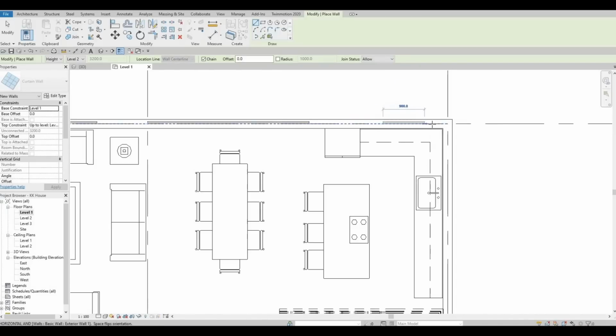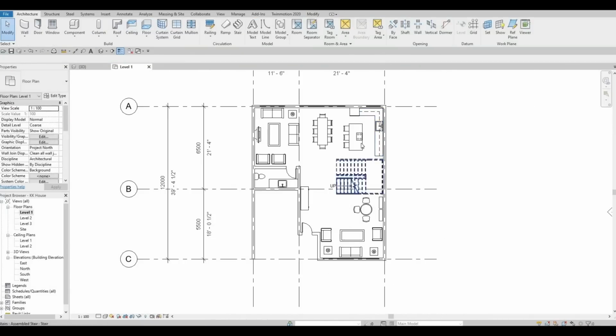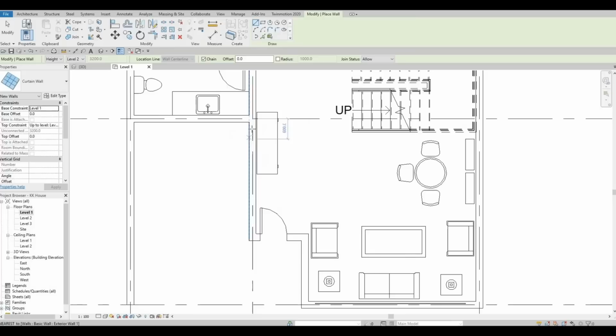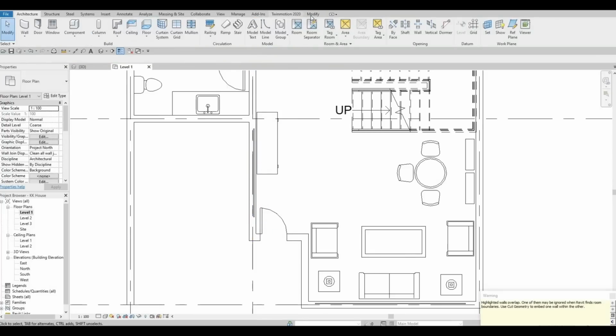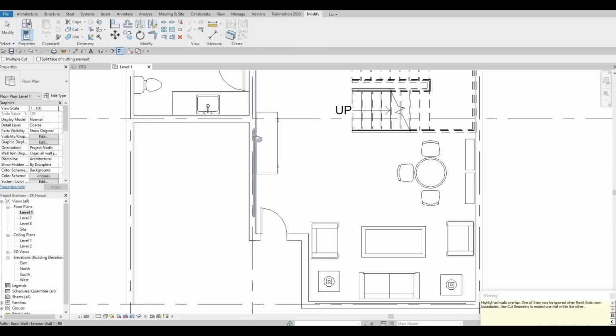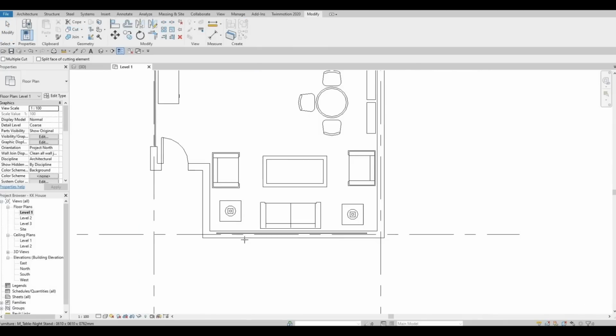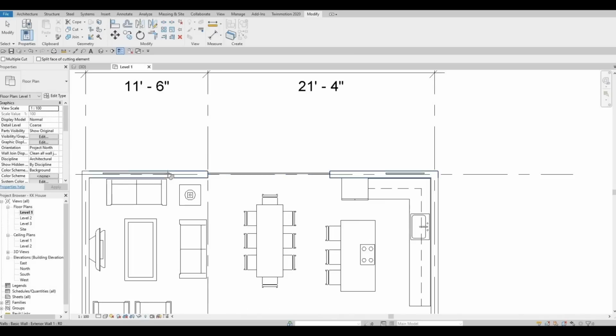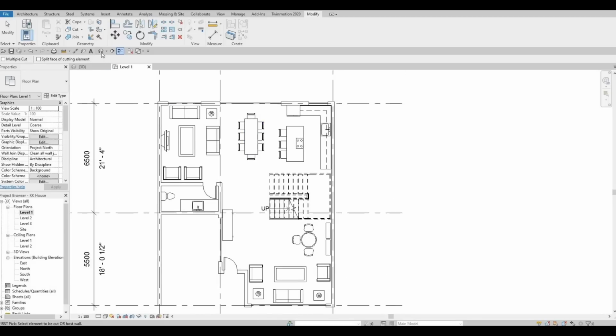And then here I'm gonna add a small one. And I'm going to add the one at the side as well. So here I'm going to click wall again, and I'm going to add it here on this side. And then after that, click modify and then cut geometry. You click the wall first and then the curtain wall. So wall and then curtain wall, wall and curtain wall.